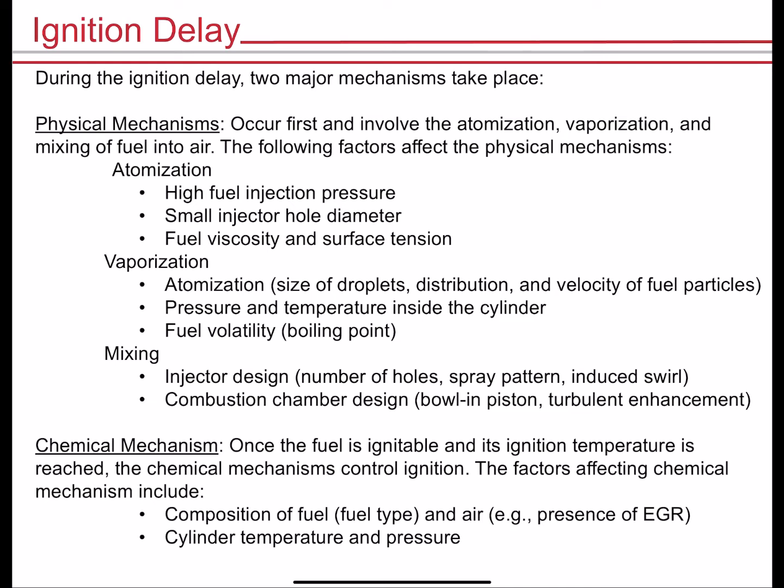Now, we always have to be really careful about this word ignition delay because it tends to get tossed around somewhat flippantly by the engine community. Combustion scientists have a very precise definition for ignition delay, and that's what we would consider to be the scientific gold standard of ignition delay. But we use it in the engine community to sort of phenomenologically represent, again, that time between when fuel gets injected and when combustion actually begins.